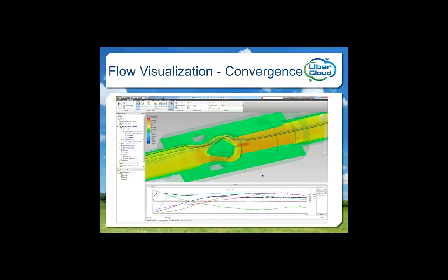The results window displays a chart of several key parameters as the program iterates the solution. Since I've asked the program to calculate the volume flow rate, the V sub X trace is of interest, and after 500 iterations did not look like it was going to settle down, and other parameters did not look like they were close to flattening out either.